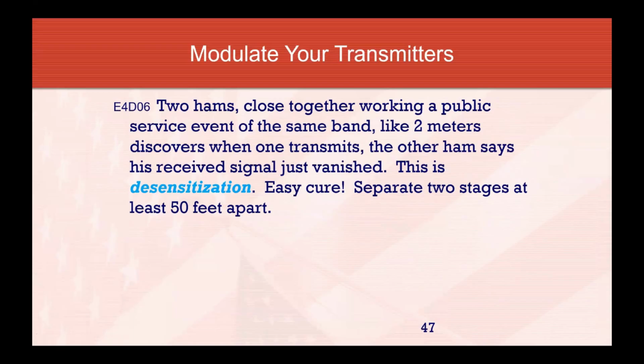This happens with Echolink. Those of you who may wonder about Echolink, our Echolink system is here at my house. The radio is a Kenwood, and of course it has built-in necessary pieces there to hook directly to the radio, and then it also hooks to the internet. So basically, when I transmit, it swamps the receiver on the Echolink side. And so anybody that's listening on Echolink hears garbage because that radio's receiver has been desensitized.